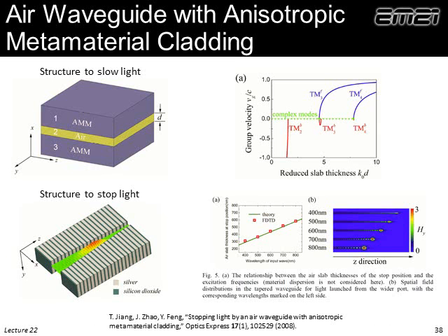There are a lot of folks looking at anisotropic materials to stop light or slow waves down. And in fact, nature only gives us so much in terms of anisotropy. We talked about this when we talked about anisotropic metamaterials. So metamaterials comes in, and that lets us do even stronger anisotropy. So this plays a role in these slow wave devices because now we can use stronger anisotropy to slow waves down even more than we could with just naturally occurring anisotropic materials.